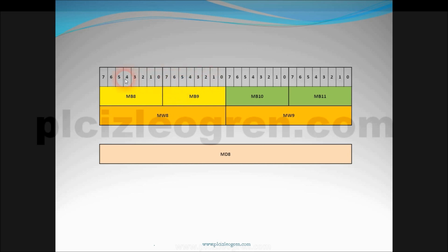What will happen now? After 9 steps, starting from M8.6 here, at every 1 second pulse, my band here moves. My piece is here now, first move, second move, third move, fourth, fifth, sixth, seventh, eighth, and ninth move. After the ninth move is complete, my cylinder detects the piece, or rather, it knows the piece detected by the sensors 9 steps before will be kicked out, and at the end of the 9th second, this piston will move downwards and that faulty piece at M9.5 will be kicked out. The system works like that.